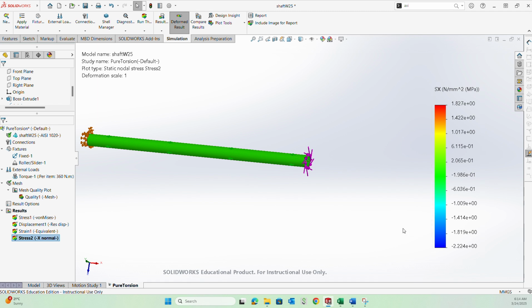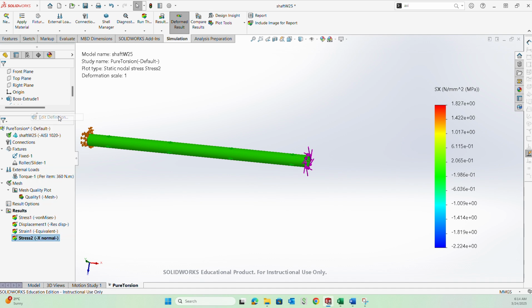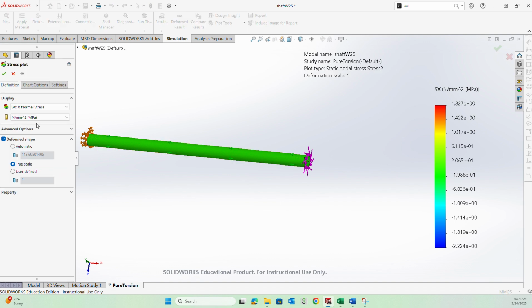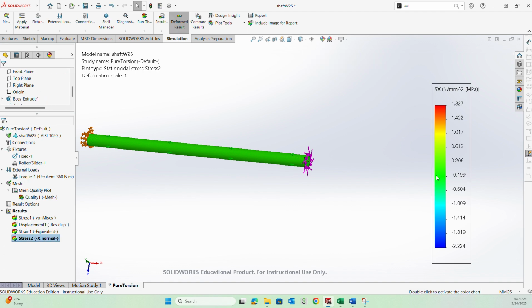Okay, so you can see here that my normal stresses are very, very low in this case, which indicates that there is no obvious problem with the model setup itself. This is a quick check on the sanity of the model, but of course we will do more detailed validation later.